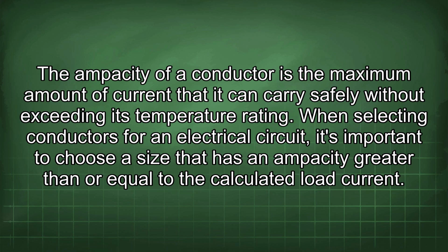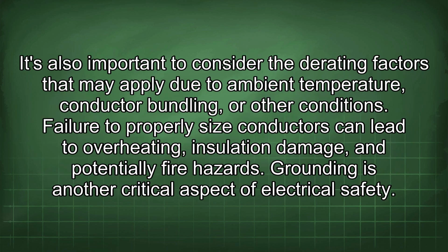The ampacity of a conductor is the maximum amount of current that it can carry safely without exceeding its temperature rating. When selecting conductors for an electrical circuit, it's important to choose a size that has an ampacity greater than or equal to the calculated load current. It's also important to consider the derating factors that may apply due to ambient temperature, conductor bundling, or other conditions. Failure to properly size conductors can lead to overheating, insulation damage, and potentially fire hazards.